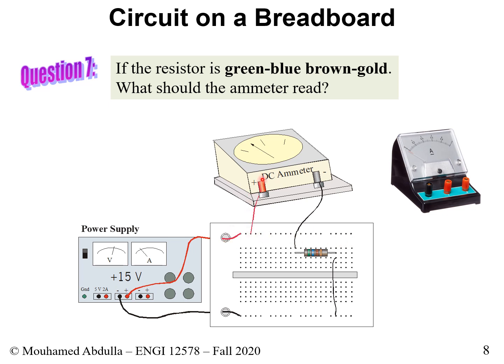and we connect it to the positive of the, if you will, the DMM or the DC ammeter. And from the negative of the DC ammeter or the DMM, we bring it to one of the locations of the breadboard. So this is a new location. We haven't used this node before. And then from the same row, they're all connected together. So this is one node.